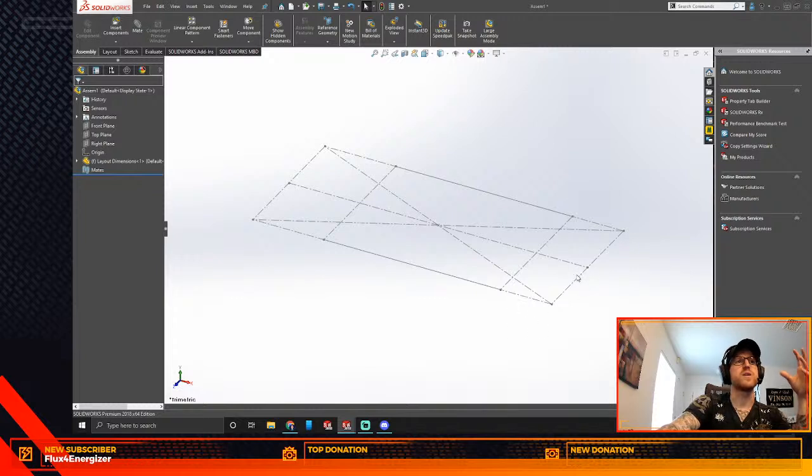And we can also have those other parts reference this specific drawing in the assembly so that we can get all the dimensions right. Now if we wanted to change stuff later, like moving back the position of the front wheel, all we have to do is change it in this reference part. And since it's parametric and we're referencing this specific part, all the rest should change too.